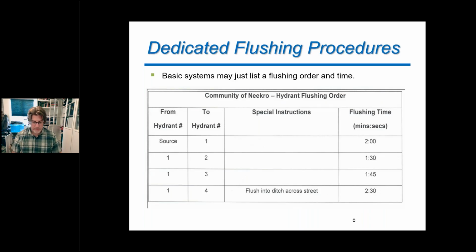And once again, if it's the first time going through, you are going to have to gather this information yourself. But this might be your dedicated flushing procedure, your plan, right? You're telling people, okay, from this hydrant to this hydrant, I'm going to list some special instructions, and then this is my minimum flushing time, right? This is how long it's going to take to do those 2 pipe volumes at this location.